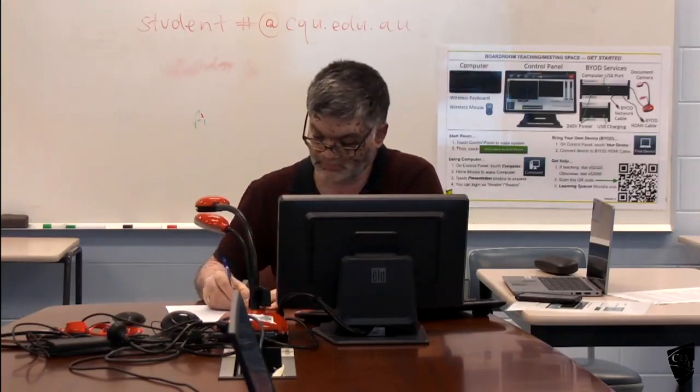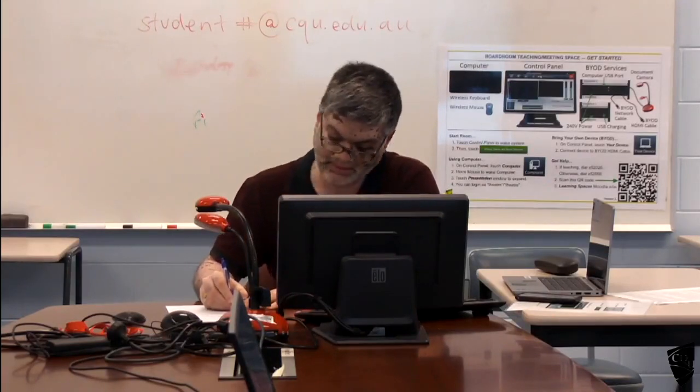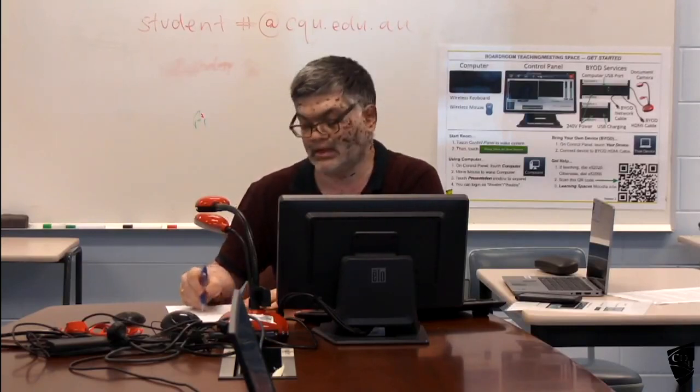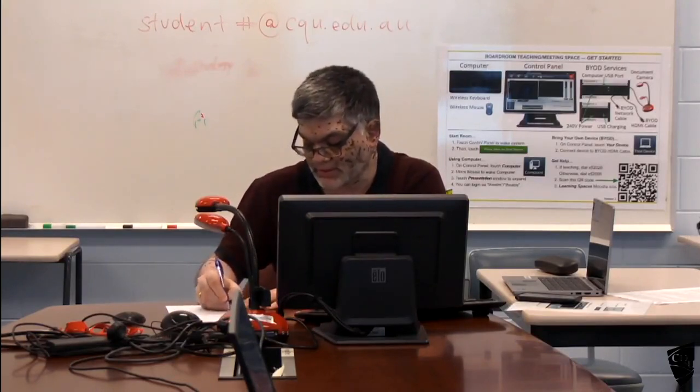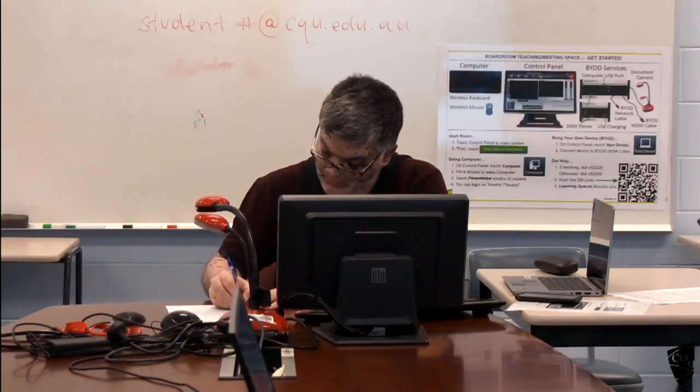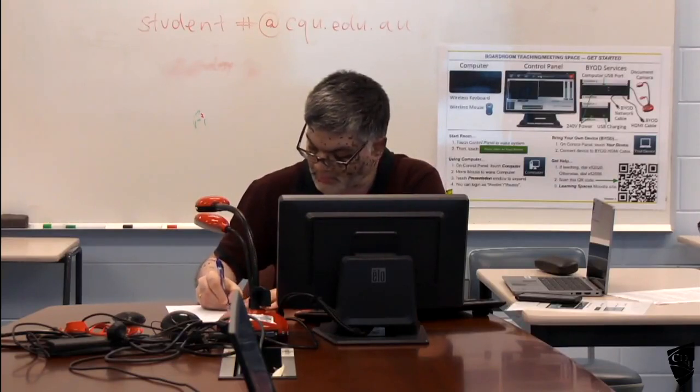Okay, mid-span. It is given in the standard, the same clause 6.10. If you go further in the same clause, you will find these equations. Both are Lx squared, not Ly.